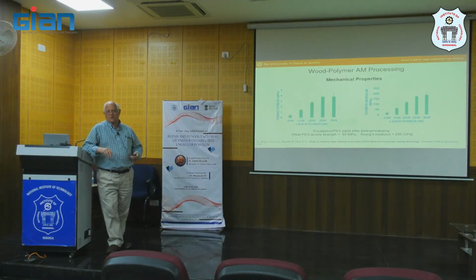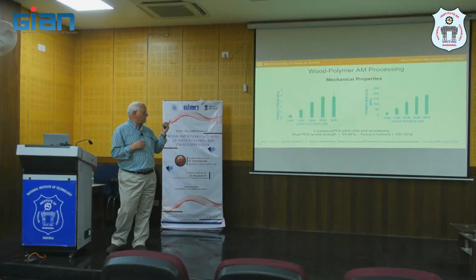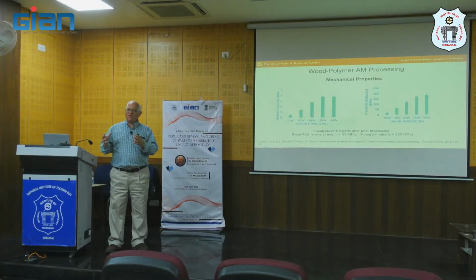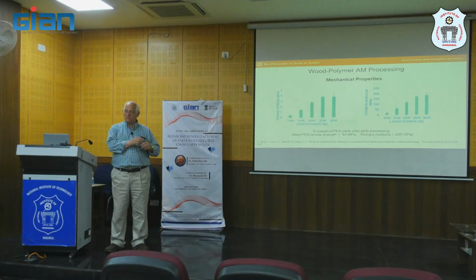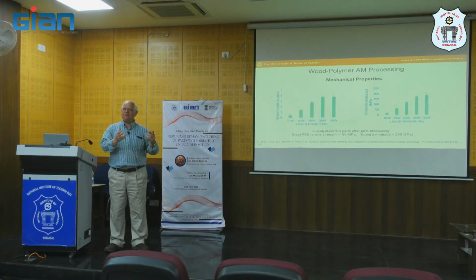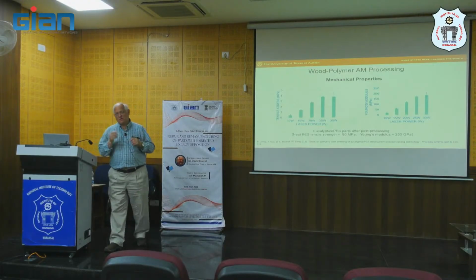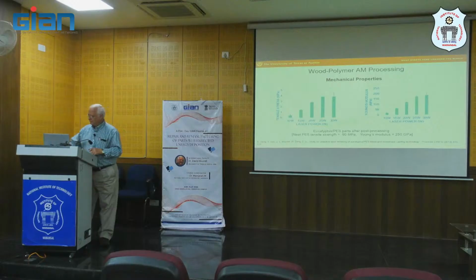So the takeaway from this is that with additive manufacturing, we can improve the sustainability by adding low embodied energy feedstocks. But the problem is that it really kills the mechanical properties, which is a real problem.